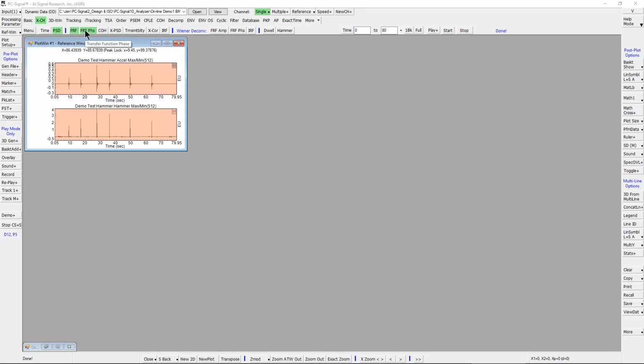Hammer test is another commonly used vibration test for structure mode identification. The frequency response function, or FRF, between two locations can be computed from a hammer excitation and a vibration response measurement. In order to minimize statistical variance, multiple hammer events are usually conducted at the same location so that data averaging can be performed over multiple hammer time frames.